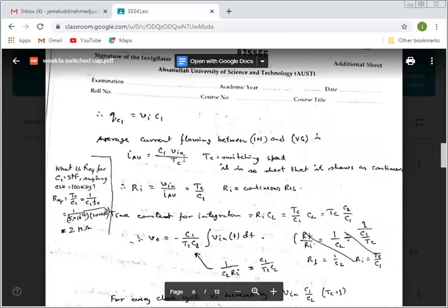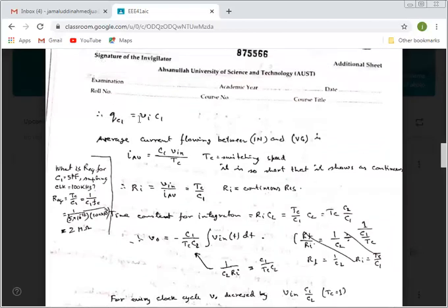So let us consider the amount of charge that is transferred. It depends on the Vin and the C1, Q equals CV. So every time we take a sample, this amount of charge moves from the voltage source to C1.